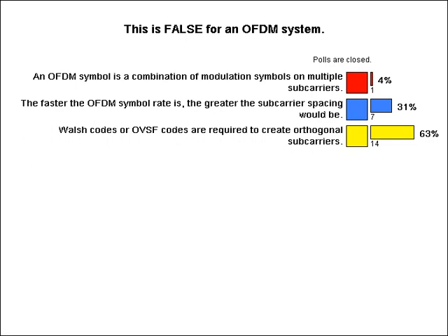One dimension is your number of subcarriers, another dimension is number of symbols. If you have shorter symbols, then you have more symbols. Fewer subcarriers but more symbols. So in a certain time period, you can send many OFDM symbols, even though you may have fewer subcarriers.